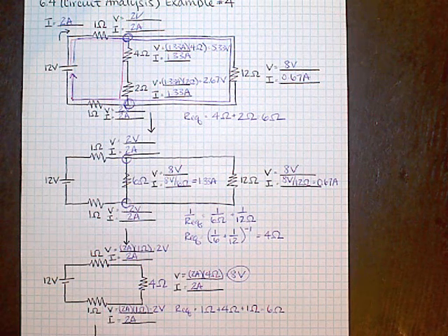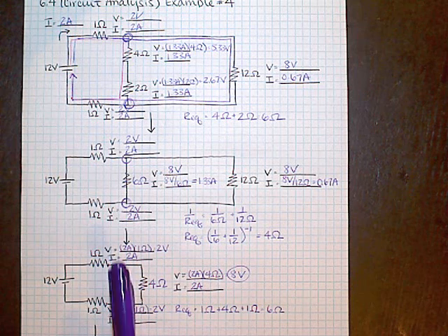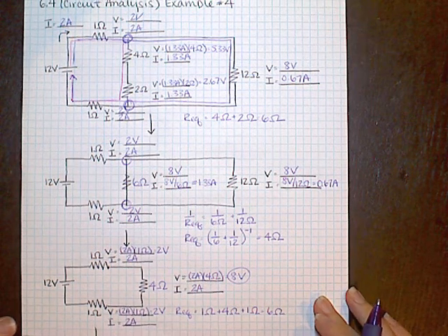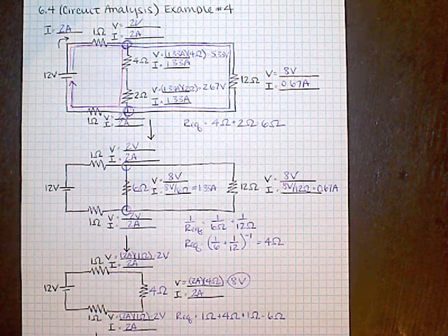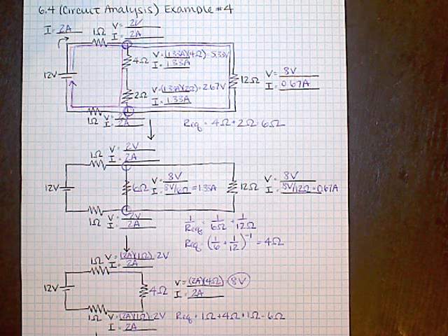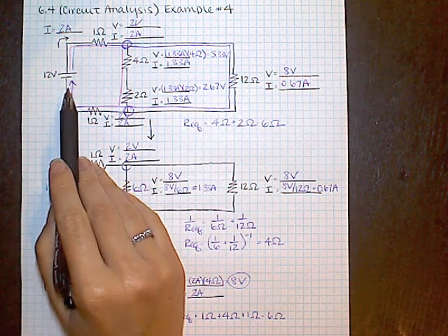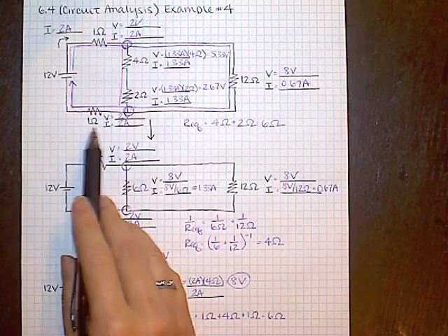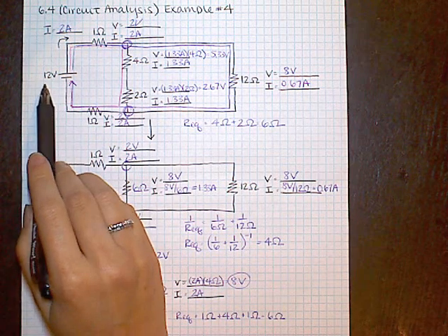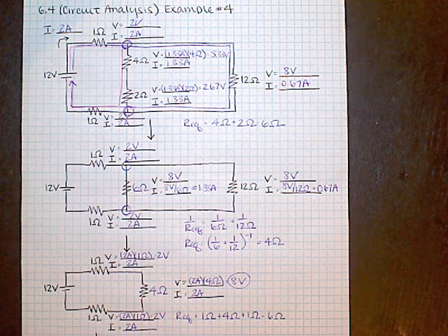Cool. All right, so now I've figured out for every component in my original circuit what its voltage is and what its current is. But if I'm not 100% confident, because I know there were a lot of places where I could have made a little mistake, what I'm going to do is use the loop rule and the junction rule to check my work. So the loop rule says that for any complete pathway from the positive to the negative terminal of the battery, all of my voltage drops along that way should add up to the voltage of the battery. So there are 2 different pathways here.